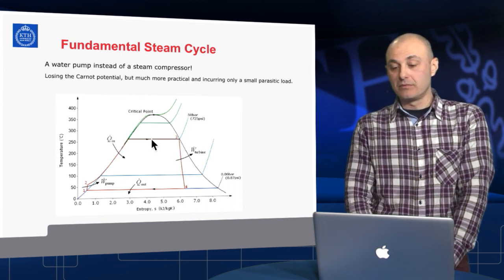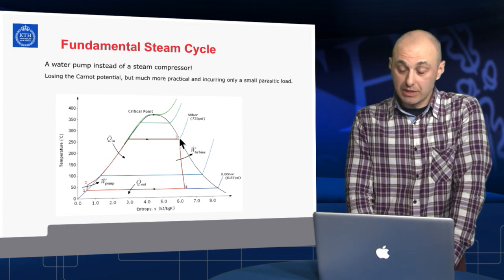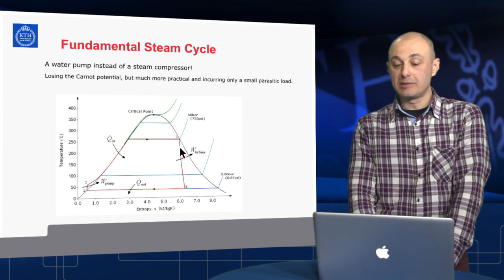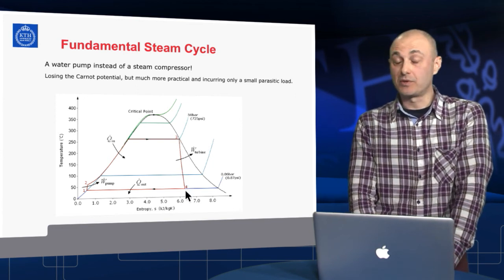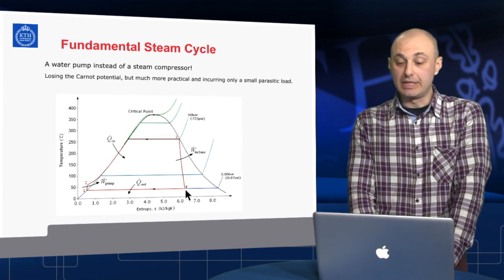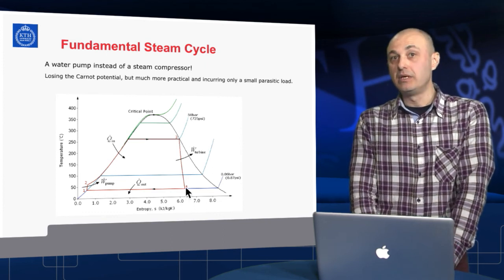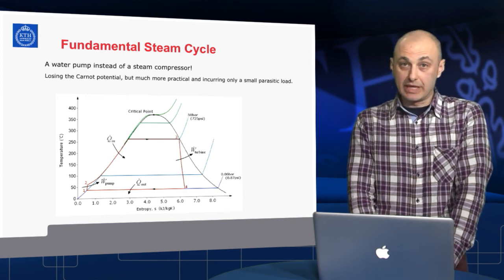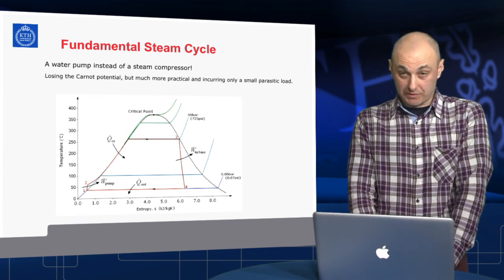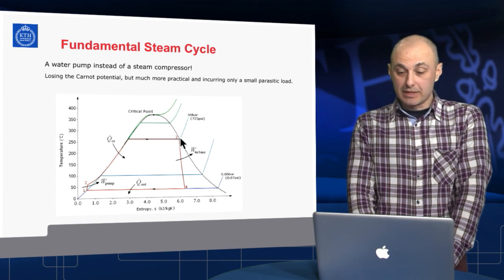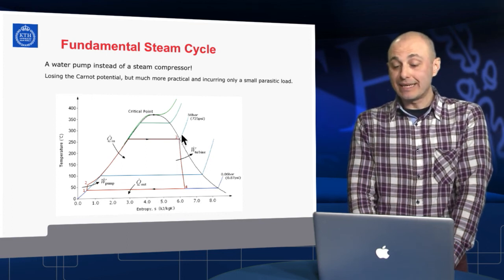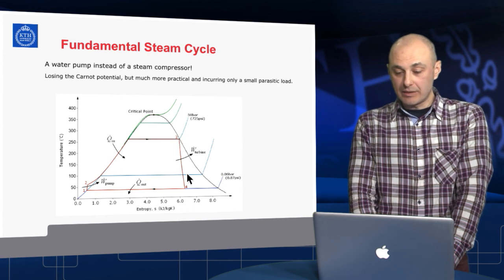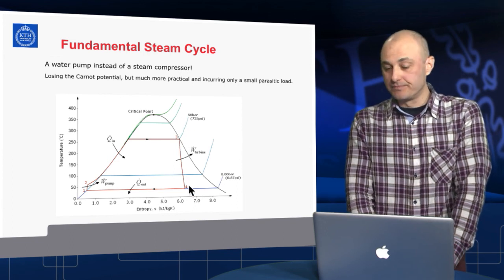All the water being converted into steam in the boiler, then expanded, and the expansion process is not tricky at all. It is possible to be performed even with a slightly wet steam, and that's what the old piston engines, like the old steam locomotives, were doing. They were expanding more or less saturated steam or slightly superheated and ending up deep into the double phase zone.